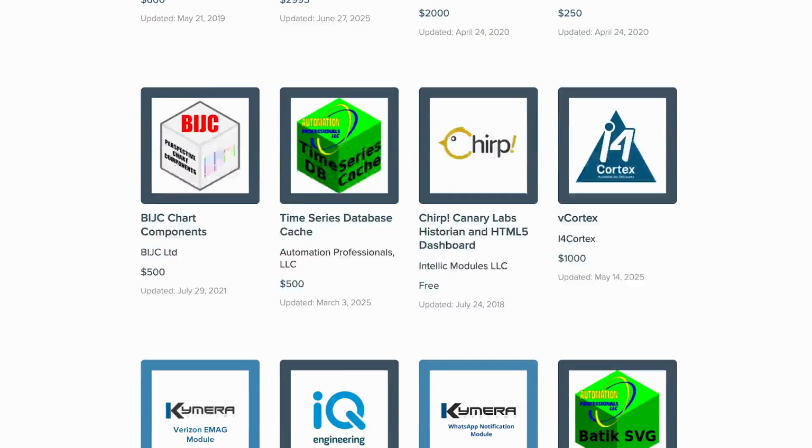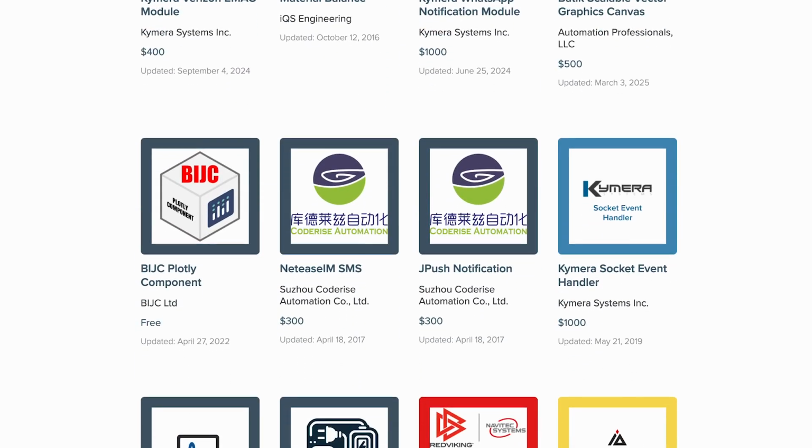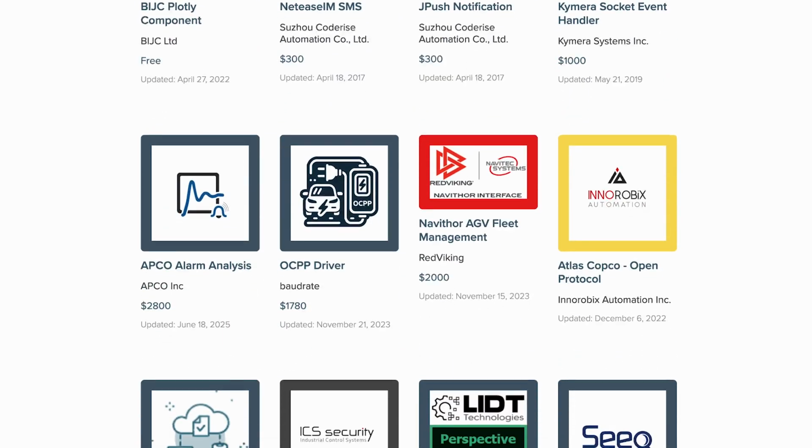Here, programmable logic controllers and remote terminal units control and monitor the devices operating at the physical process level below. In controlled environments like plant floors, organizations generally opt for PLCs, while RTUs are mainly used in remote environments with less operator oversight. Ignition can reliably connect to practically any PLC at this level between its suite of core drivers and support for both OPC UA and MQTT communication protocols. For any devices at the process control level not directly supported by Ignition, the public API allows third parties to create their own drivers like the ones available on Inductive Automation's third-party module showcase.